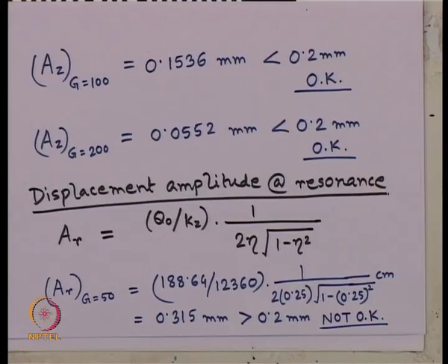Now, here I want to mention one thing. This displacement is actually not going to occur. Which displacement is going to occur? Displacement at operating frequency, because the machine will always run at its operating frequency. So, whatever is the displacement for the machine plus foundation system is going to occur, that will be because of the operating frequency. But still